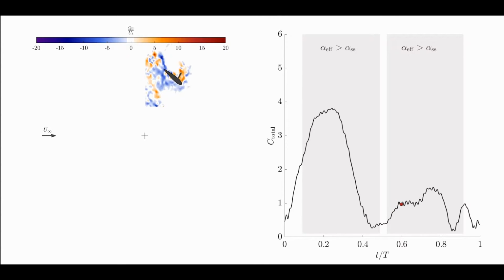We do note a second accumulation of vorticity in the second half, resulting in a local force maximum. However, it lacks coherence to be considered a second dynamic stall vortex. As the revolution ends, the flow reattaches and the blade enters upwind conditions once again.